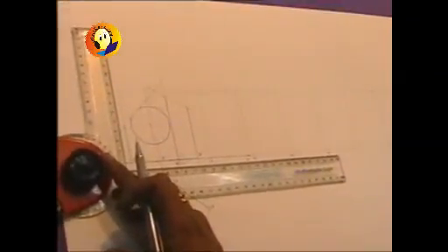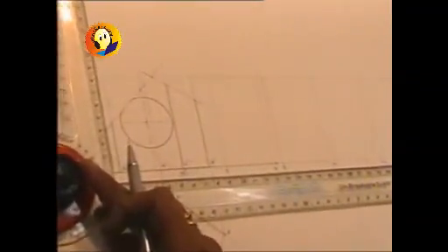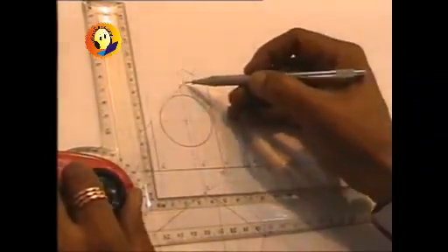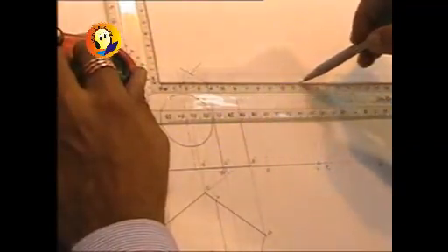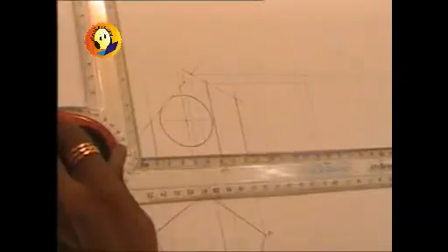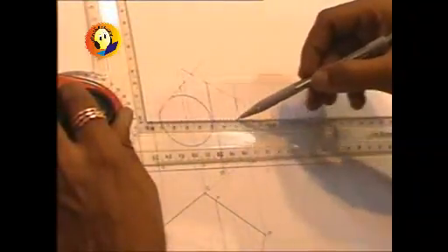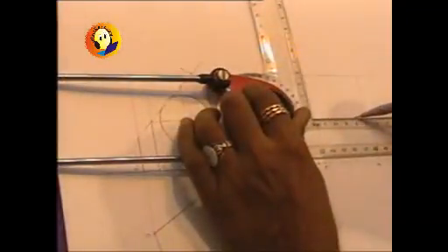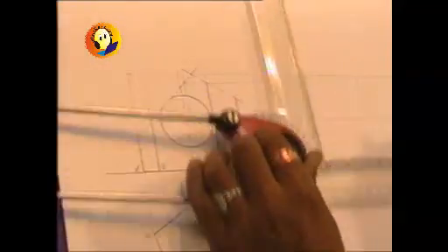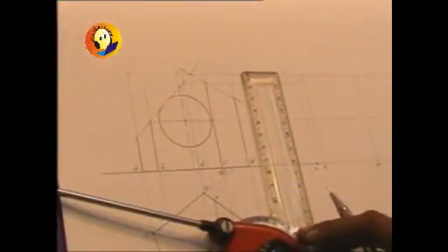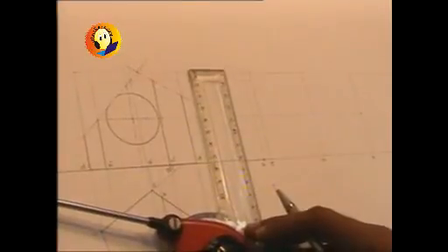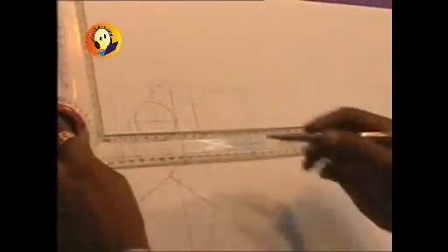Let us proceed one by one. First of all, that 45 degrees plane which has been cut or is cutting the generators. First generator that is cut is EV at this point. So we can draw the path and mark point on generator E. Then generator BV is cut. So even that point can be taken and marked on generator B. We get the point on generator B in this case. And then point on generator A.